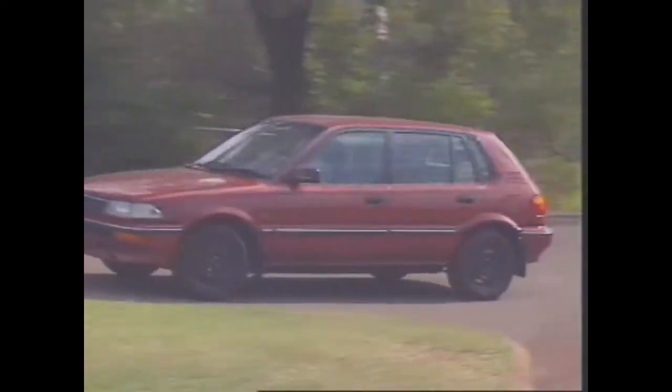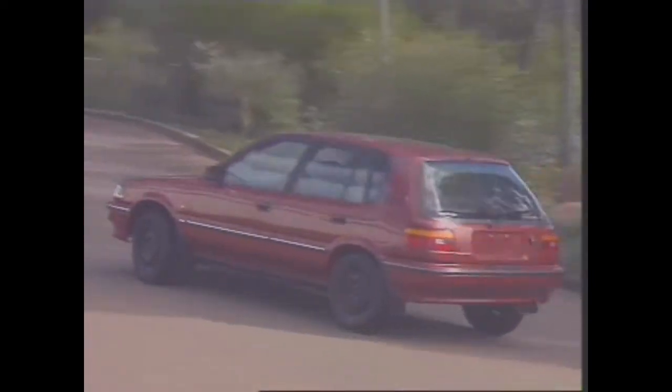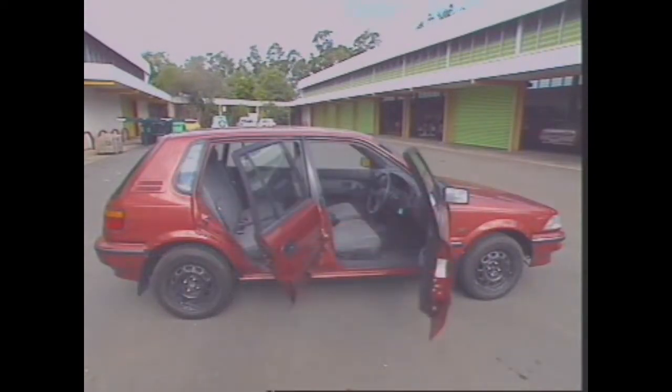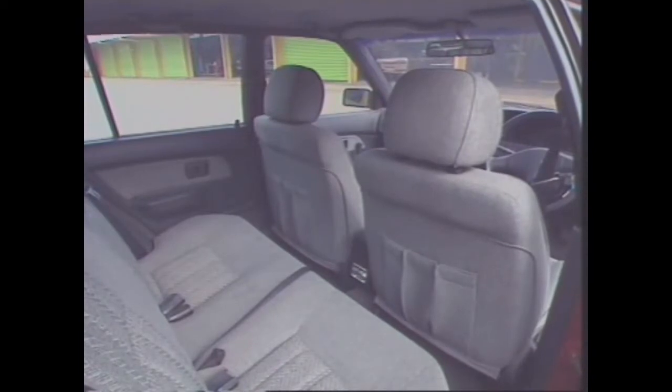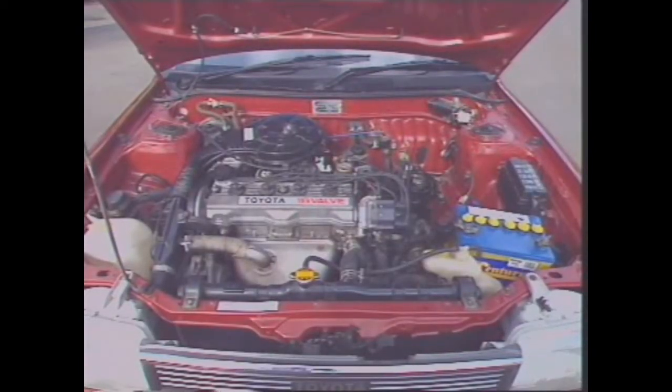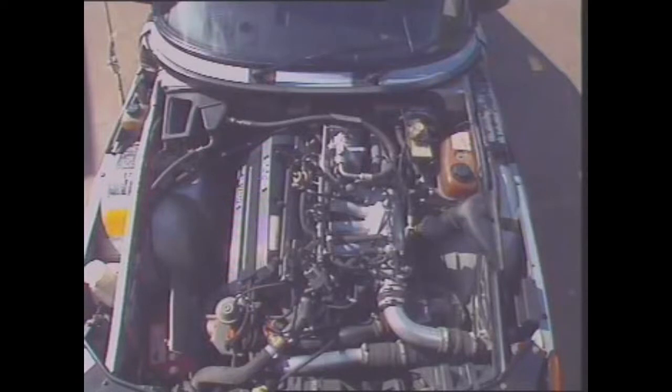Front-wheel drive vehicles use the front wheels to pull the vehicle along. In light passenger vehicles, it gives lighter body weight and increased interior room. The engine and transaxle are at the front and can be mounted laterally, that is, the engine is parallel to the front axle, or longitudinally, where the engine is in line with the center line of the vehicle.